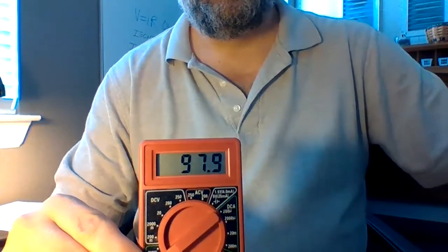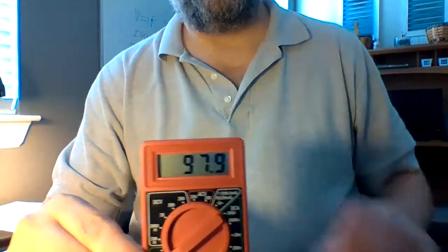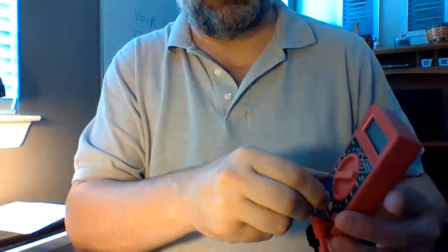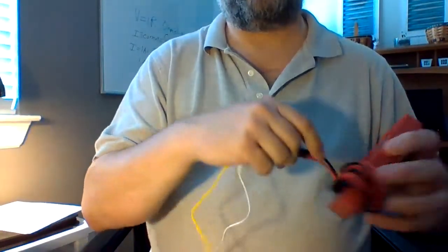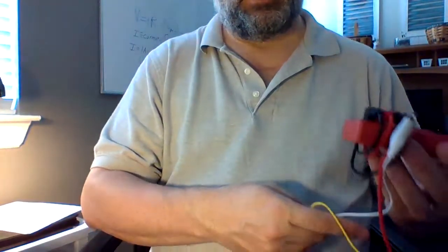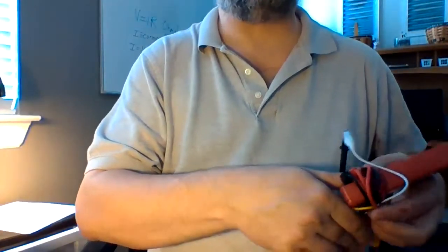Now, why is that? When we get to resistors, we're going to learn that there are some standard resistor types. And guess what? One of them is 100 kiloohms. And so what that means is that was a 100 kiloohm resistor. You'll notice that it was well within the tolerance, which you will learn when we learn markings. That was within 5% of the manufacturing tolerance.